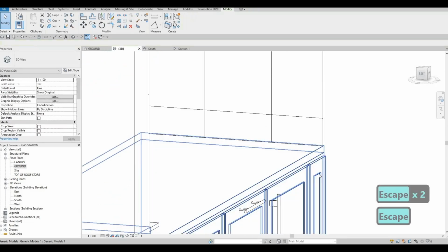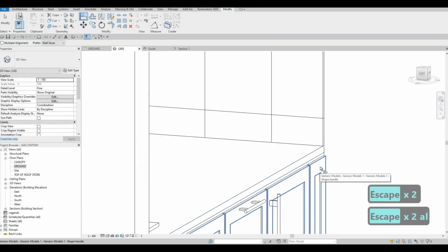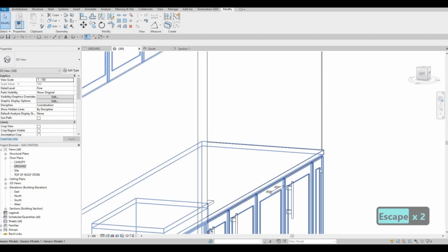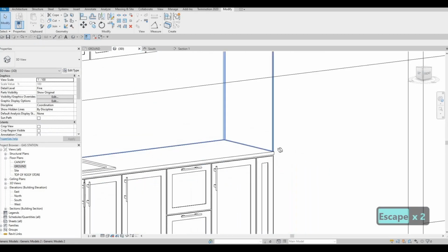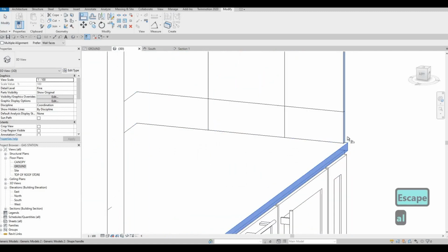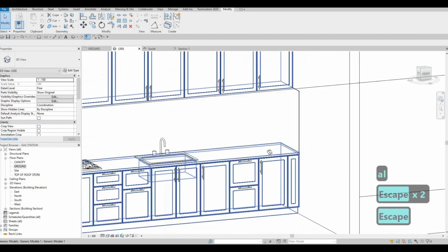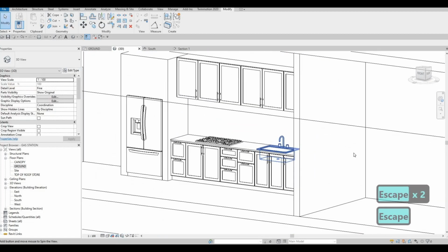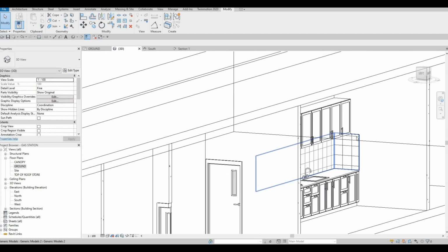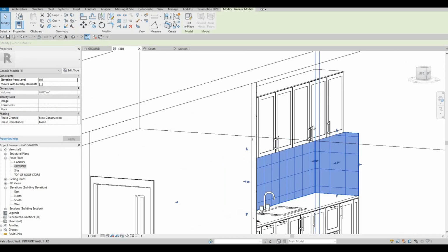I want to align this one as well, so AL, align the wall or the door of the kitchen or the base cabinet, and then align it from the top so that at least it's indented like that. We could also put this one right there as well. That's why I love model in place, because of that idea that we could basically edit anything once we're in this phase, and it's easy. If we want to make this one as well, why not?